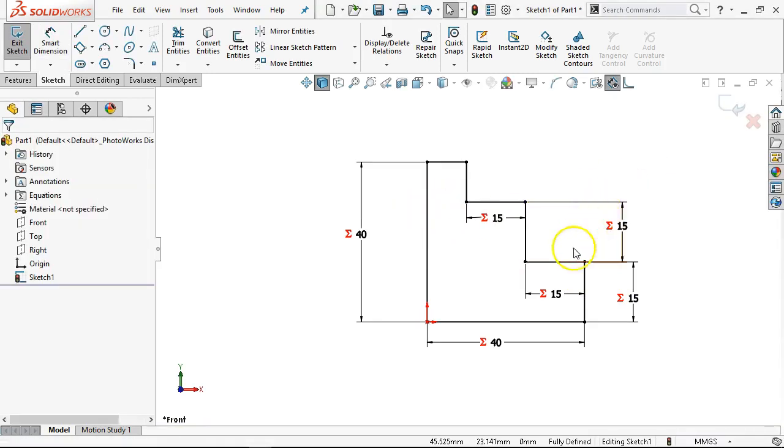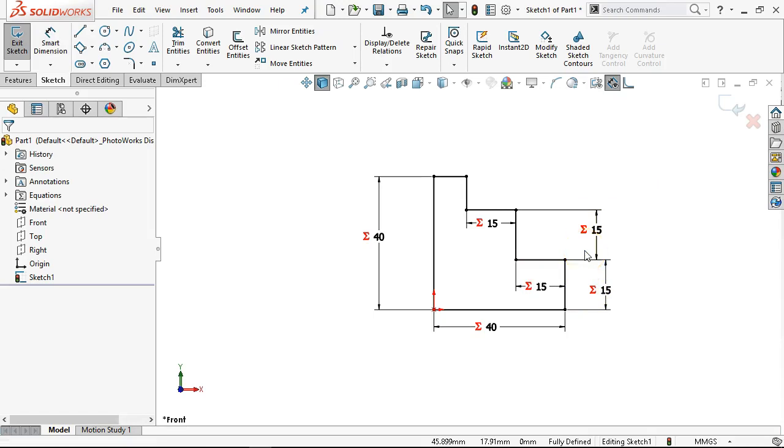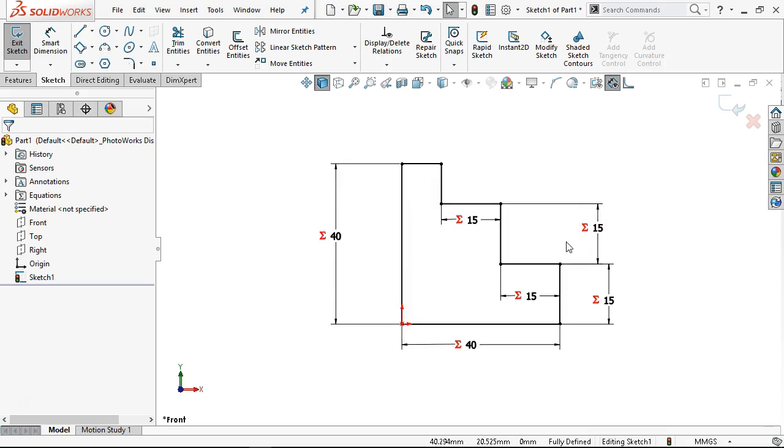Okay, so this is going to be very similar. Let's see, I probably should have looked at that one first. Maybe we'll do that with some fillets. Anyway, this is going to be similar to linking values. The advantage, though, is that the global variable can participate in the extrusion. The global variable can participate in any of the other geometry and across features. It's not limited to this sketch.